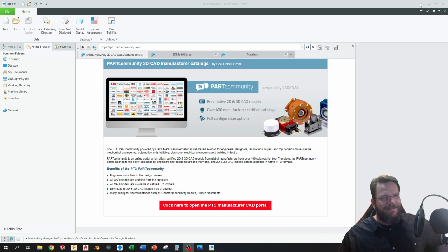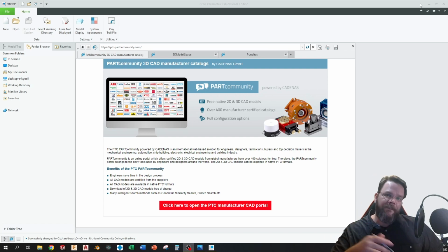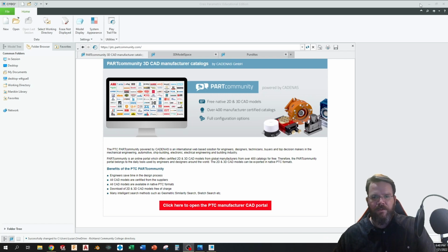All right, back to the steps. Step 3 would then be to create a 2D sketch of that base feature. Step 4, apply any constraints or dimensions that need to be added to that sketch. And step 5 would then be to convert that sketch into a 3D feature by way of an extrude or a sweep or a revolve or whatever method you're going to be using. And then for the rest of the model, you're just going to repeat those steps over and over again. You'll go back to step 2, only instead of determining a base feature, you're then going to determine what feature comes next. Create a 2D sketch, add your constraints and dimensions, create the 3D part or feature, and so on until your part is complete.